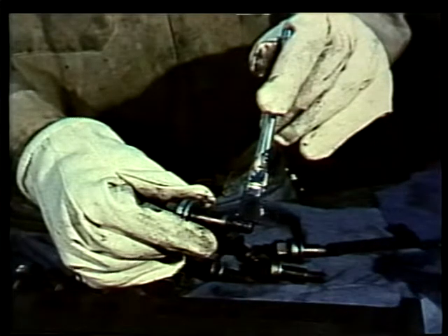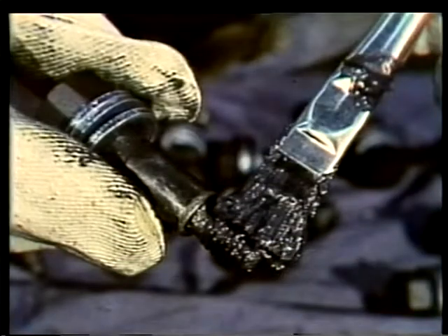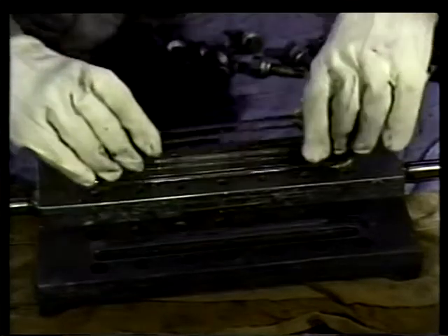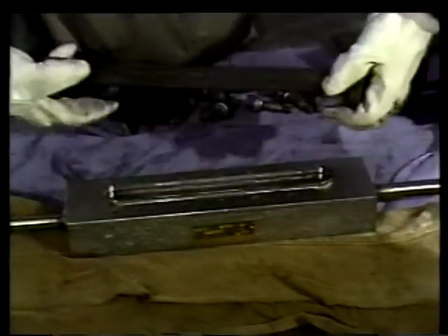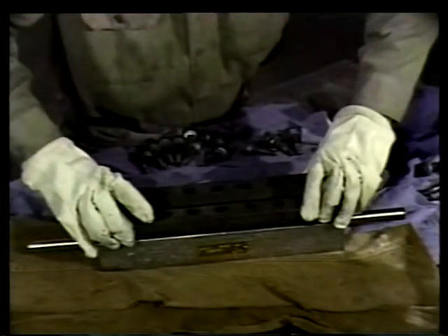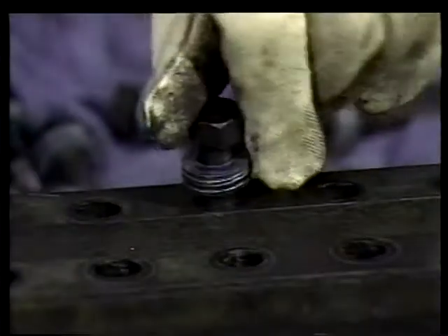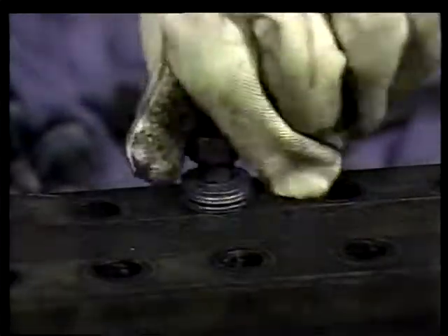Lubricate the threads of the bolts with a high-temperature lubricant like Molykote. This is very important because if it's not done, it will be difficult to disassemble the gauge the next time it's overhauled. Place the cushion in its groove in the cover plate and put the cover in place according to its match marks. Then install the bolts and washers. The washers act as springs and must be replaced correctly.